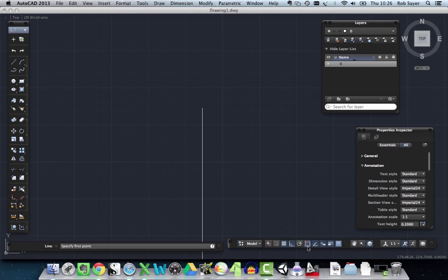And this particular snap we want here, there are different snaps, but the one we want is object snap, and I've got that turned on at the moment. It's a square on the bottom little toolbar, a sort of square with a point on it, and if it's blue it's turned on. So that means that now when I hover over the end point of that particular item I've just drawn, my next line will start at that point. Now I'm going to take this back, say 1 meter.